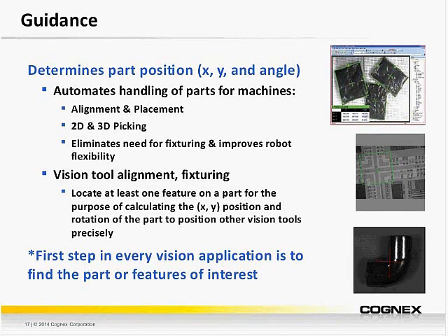Machine vision systems locate parts in 2 or 3 dimensional space and provide the robot controller with position information to adjust the robot path. This achieves far greater speed and accuracy in applications such as placing parts on or removing parts from pallets, picking parts from a conveyor and placing them in a package, locating parts and aligning them for assembly with other components, or placing them into a work cell, or even picking parts out of bins and aligning and feeding them